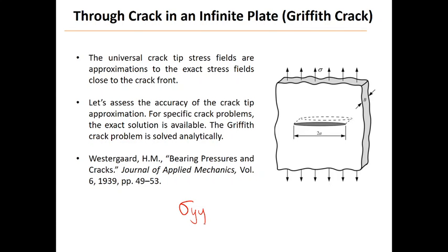Sigma yy from the Westergaard solution is going to be sigma times x over the square root of x squared minus a squared. In the Westergaard solution, the origin is defined at the center.